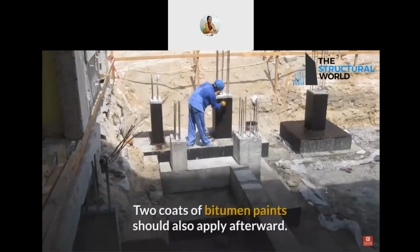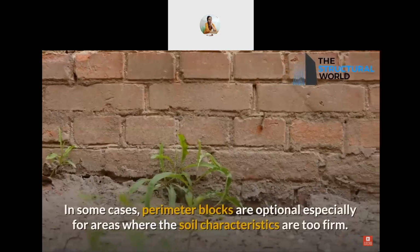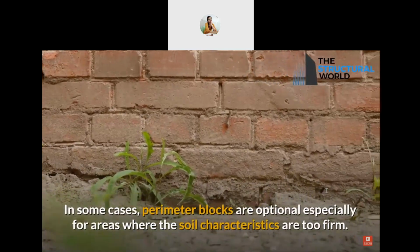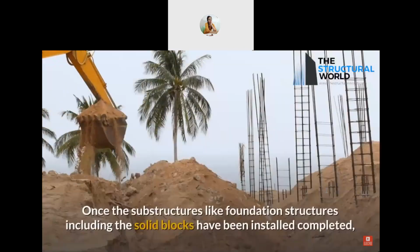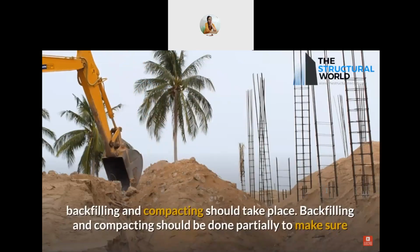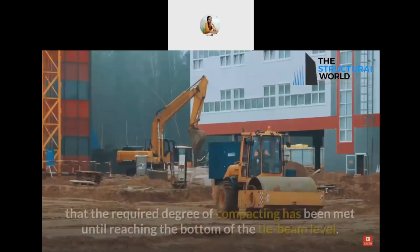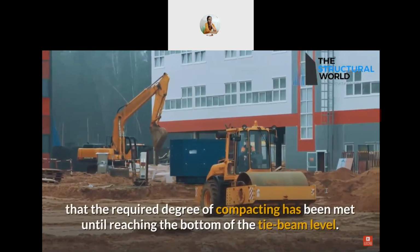Two coats of bitumen paint should also be applied afterward. In some cases, perimeter blocks are optional, especially for areas where the soil characteristics are too firm. 9. Backfilling and compacting. Once the substructures, including the foundation structures and the solid blocks, have been installed, backfilling and compacting should take place. Backfilling and compacting should be done partially to make sure that the required degree of compaction has been met until reaching the bottom of the tie beam level.